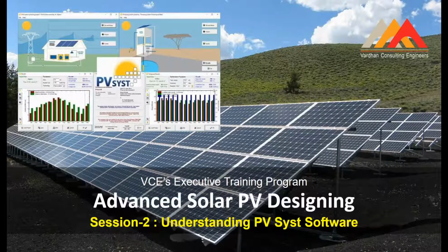So how are you going to connect? How many modules do you connect in series, and how many other modules do you need to connect in parallel? The modules connected in series are called a string, and the modules connected in parallel are called arrays. So how many modules do you want to connect in series? Is there any thumb rule? Okay. Yes, there is a thumb rule. For the number of modules you can connect in series, in series the current is the same, but the voltages add up.